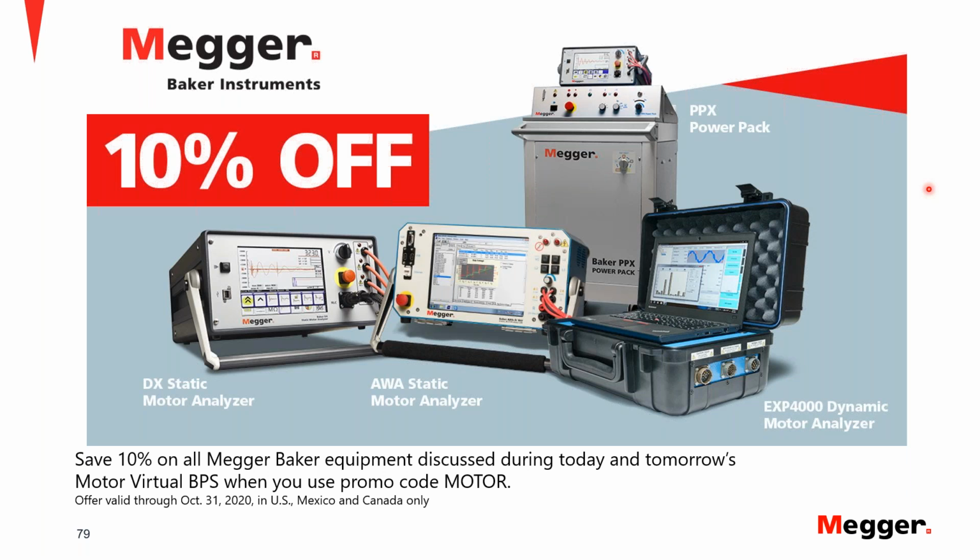So any change in the inductance will change the frequency of the resulting waveform. Now, in a three-phase motor, when you're testing, you will be testing line 1, then line 2, then line 3, which are phases A, B, and C, or depending on where you are in the world, how you represent those phases. But they will be phases 1, 2, and 3 of the motor. For each of those tests, you have a different circuit inside of the machine, but the resulting inductance should be very similar to each other.